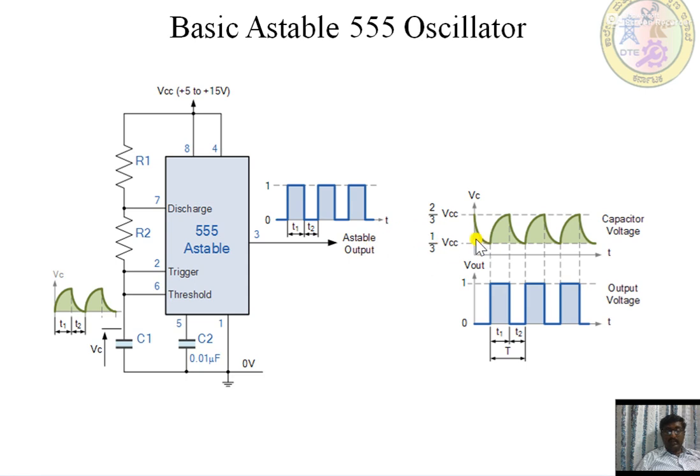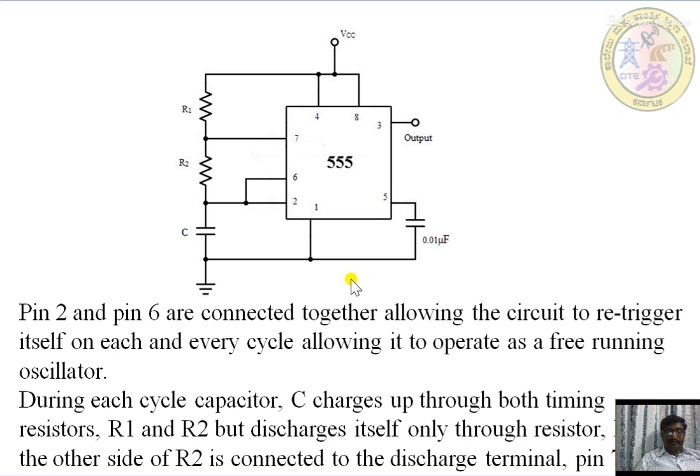So we are comparing the voltage, that is 2/3 of the capacitor voltage and 1/3 is the point. This is the point where it will be charging, discharging, and charging, discharging, and during this we will be getting a stable output of 50% to 100%. So 0 to 1, that is T1 and T2, and capital T, the time cycle, is T1 plus T2, which we will cross-check later.